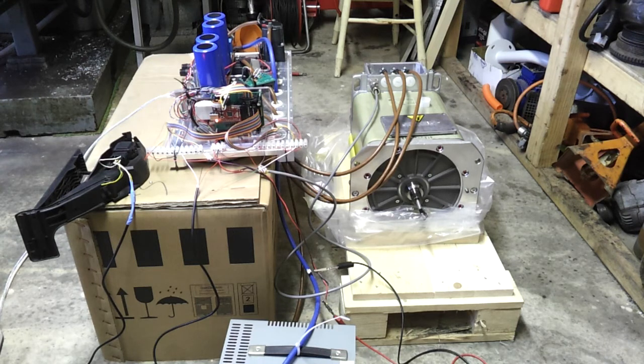So you just give it a pulse and that starts the inverter, and if we get an overcurrent or any other potential shutdown, that basically drops out the contactor. But when I had that wired up, it was just bringing it back on continuously, so it was causing us a bit of a problem, which we've now solved.